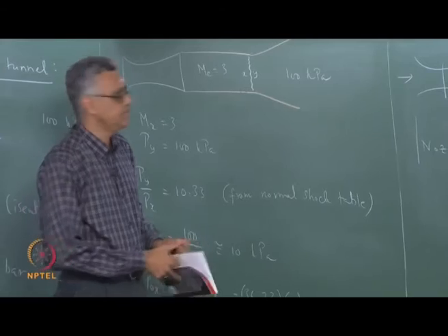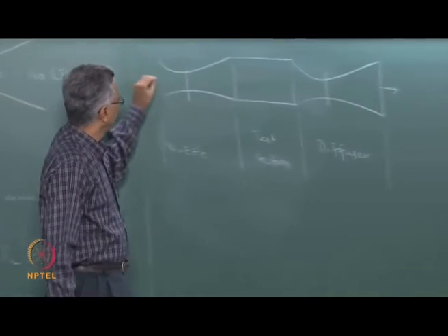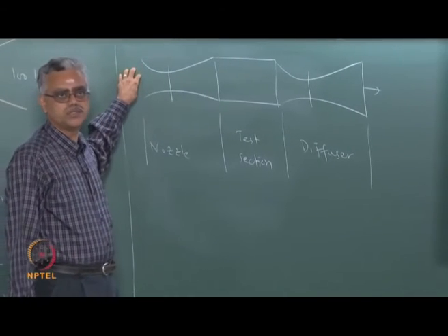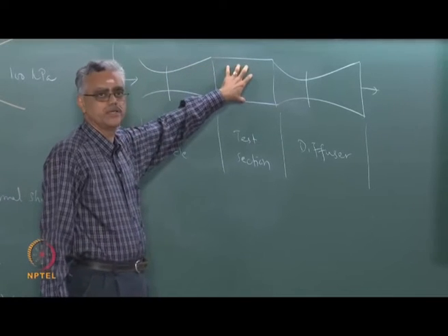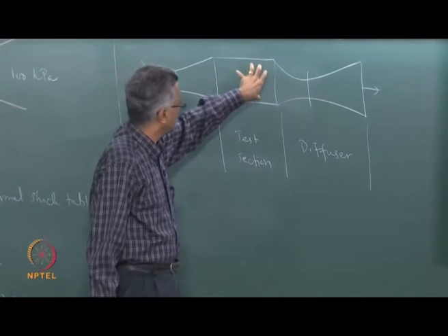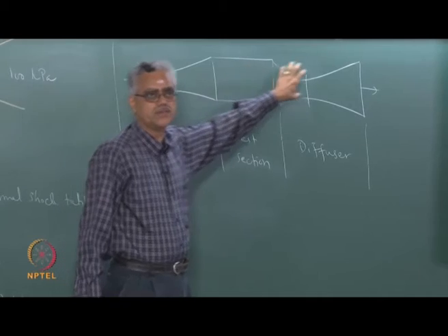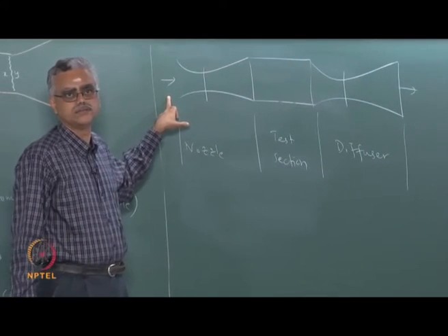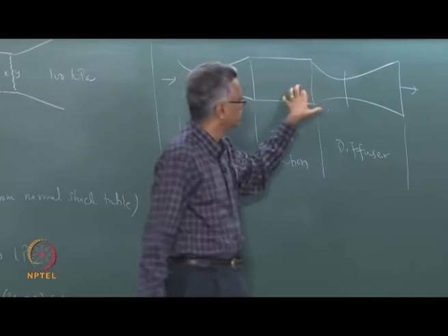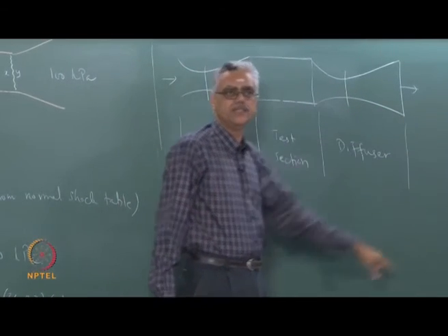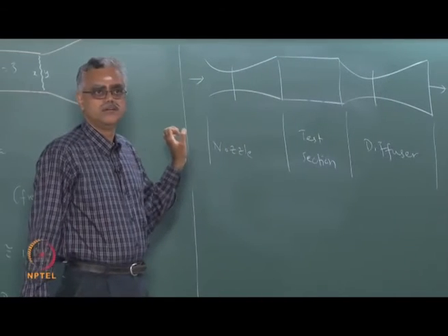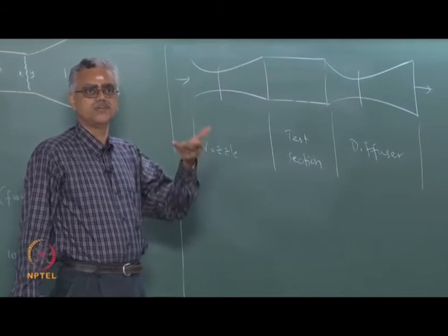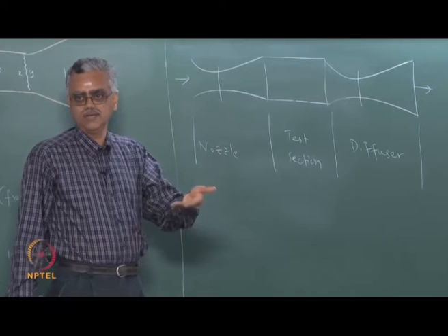Okay. The idea is during operation, the air comes in at a certain static pressure, goes through, becomes supersonic, and then if I am able to recover the momentum of the air and convert that to static pressure, I can feed this air back into the inlet here. Or I am sorry, if I recover this as the momentum, I can feed the air back into my storage tank, because I have now converted the momentum into high static pressure.